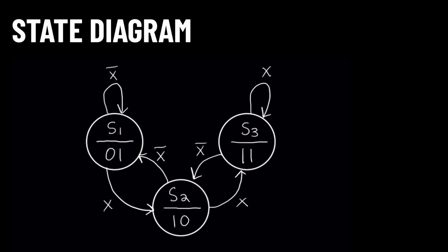I will include an additional transition arrow into S1. This shows that an active low reset signal can be used to asynchronously put our circuit into the reset state, which we defined as S1. This signal will not show up in our state or transition table, but should be used as a reminder to wire up the asynchronous clear pins to an active low reset signal. Our state diagram is fully defined because we know what the next state will be in each state for every possible value of the input variable. There are no input conditions that would lead to an unknown outcome.